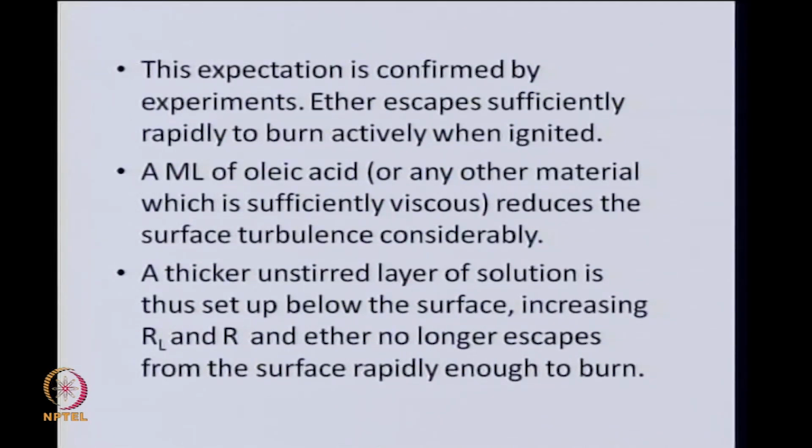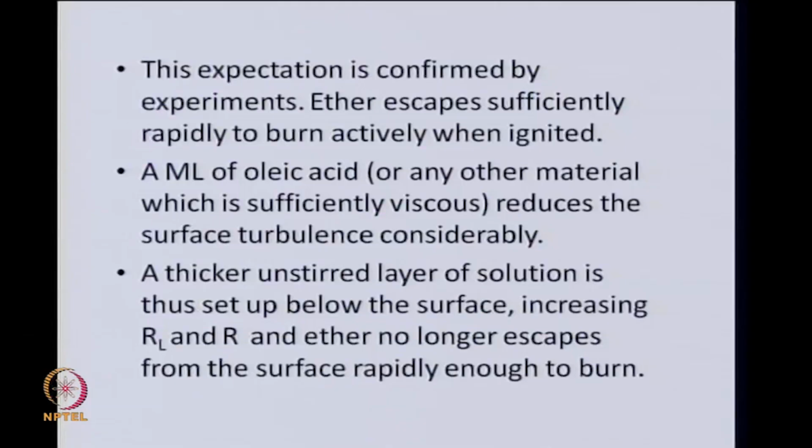However, if you introduce a monolayer like of oleic acid or any other material with high enough surface viscosity, then these unsteady movements in the surface could be considerably reduced, and therefore, the liquid phase resistance will also be kept at a higher value, because effectively a larger liquid depth below the interface will be remaining stationary or unperturbed.